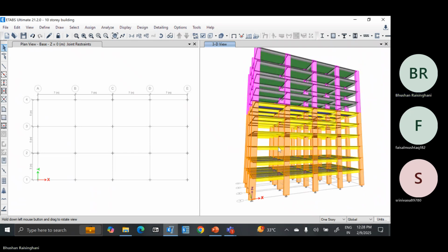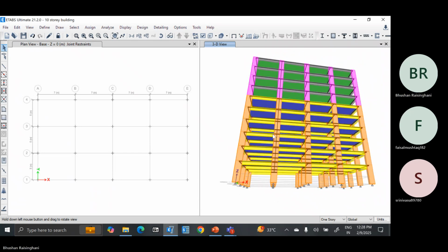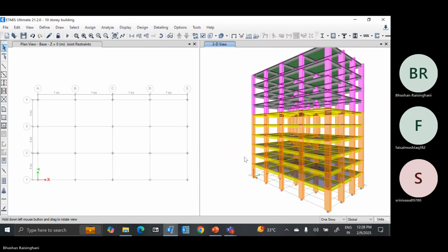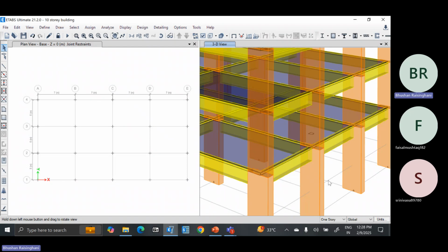Here you can see one additional grid is generated in between. In this grid, I can draw the beams where the staircase is going to come. Right now, there is no planning. That's why I have not modeled the beam. And it is a reference plane. That's why you can see the column is directly modeled as one element. It is not dividing at this element. So a reference plane is necessary for creating a multi-floor or staircase beam, which is not dividing the floor, but you want to model something there.